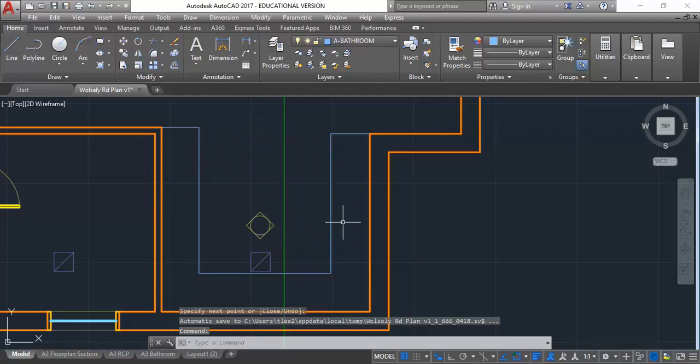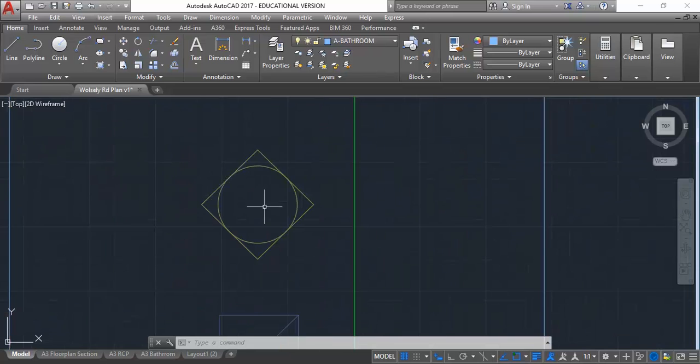So if that's your basic kitchen plan, then you could probably have 3 elevations, one for each face of those benches, because you don't really need an elevation to show the ends of those bench units. So you could just have 3, in which case you'd have a symbol like that, with the top one missing.